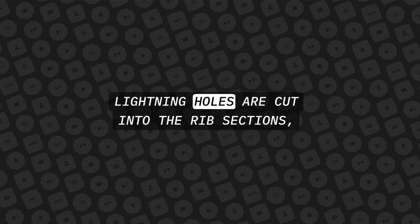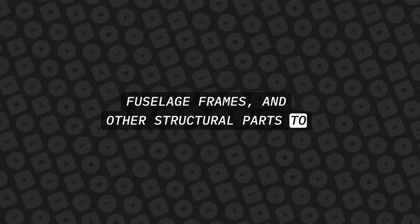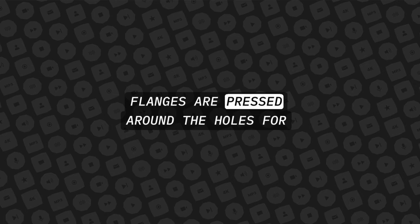For a 3/32 rivet, a number 40. For a 4/32 rivet, a number 30. And for a 5/32 rivet, a number 21. What is a lightning hole? Lightning holes are cut into the rib sections, fuselage frames, and other structural parts to decrease weight. Flanges are pressed around the holes for strength.